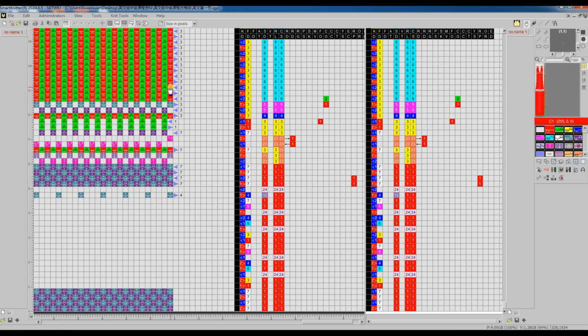Then, body yarn feeder 3 is brought in and starts the casting on. You can see the clamp and scissors action here. Clamp 1 and 2 release the yarns, meaning they both are opened. 1 row of 1x1 ribs is knitted, followed by 1 revolution of 1x1 tubular stitches.